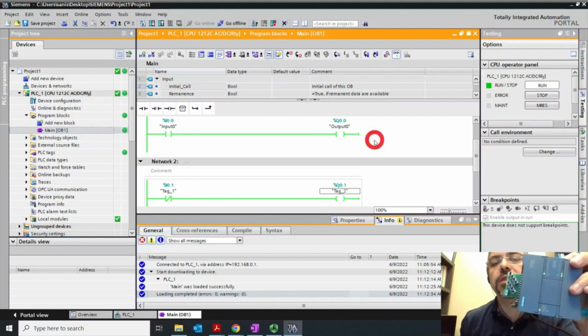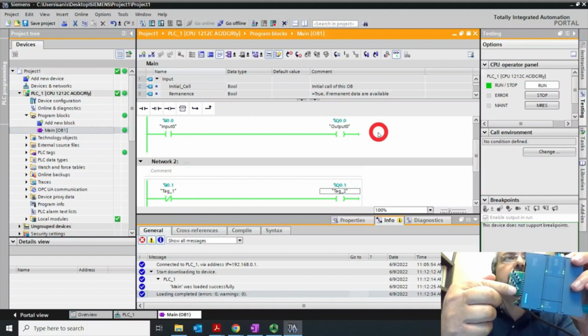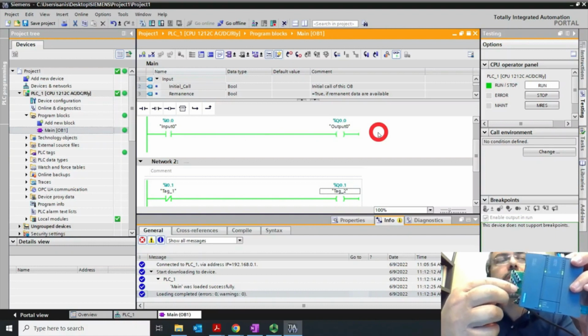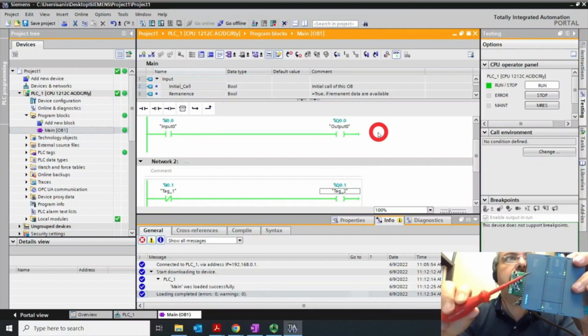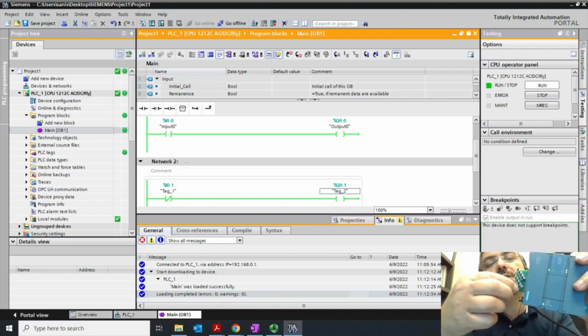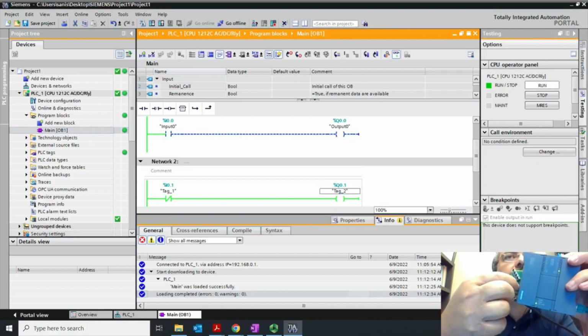So let's double check that for both of them. Let's do the first one, these guys. Just watch the simulation and what happens on your PLC at the same time. So this is a little guy. You tell me right now what I have in input 0. Right now I have 0. Right now I have 1, right? Based off this small LED that is going to turn on and off. So let's check. Input 0 is 1. What should happen? This is normally open. That means normally open whenever it is, let me just see, it is 0 or 1. Yes, right now it is 0. So see, right now this is 1 and this is 0.